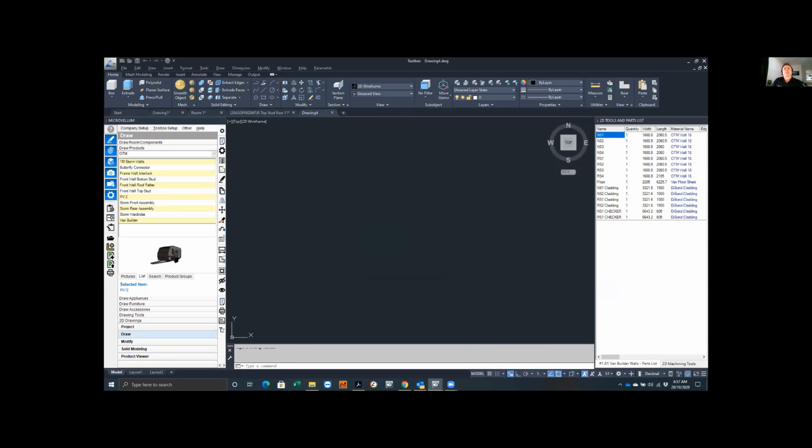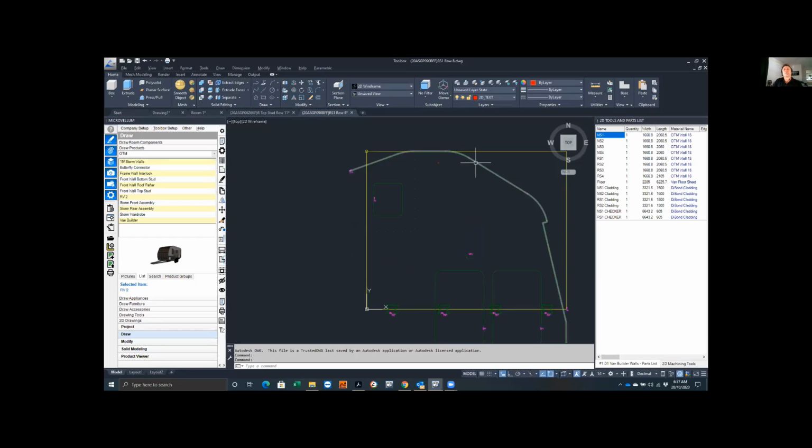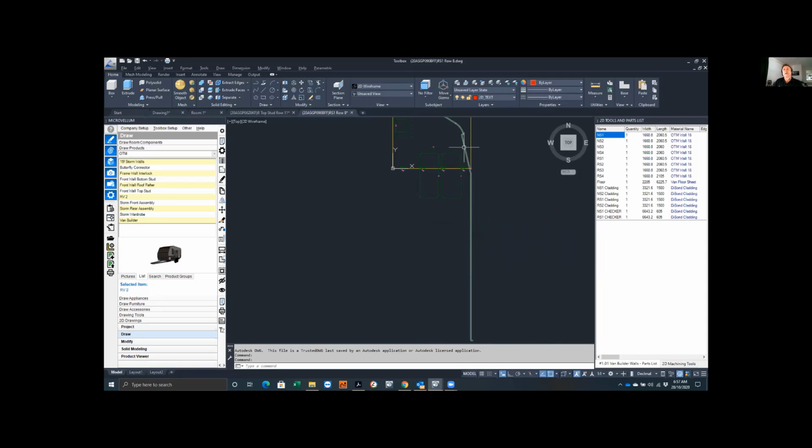So they just lay the plywood down. So if you look at this plywood, this van looks kind of weird with all these routes going off the page, but that's a virtual route that's creating that line. So wherever that virtual route ends is where it is, but once it nests, it'll only go to the edge of the sheet. So you would never see that on the nest pattern, but you can at least then get an idea of where that panel sits within the whole van. So the whole shape of the van is created by virtual routes.